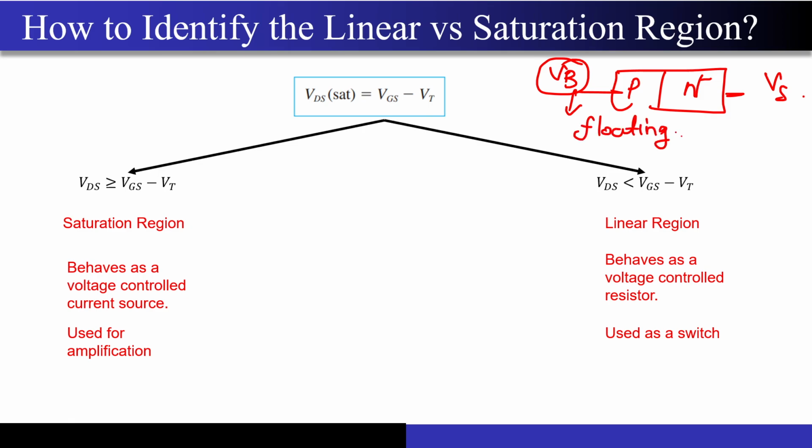See, when you want to apply some voltage to a node, you generally connect it to a voltage source, right? And then you apply a certain voltage. Let's say this is my V battery, correct? Now you are telling me don't connect anything over here. Don't even take this terminal out. That means this node is left floating, and it can take any voltage. It can take any voltage because it's a floating node.